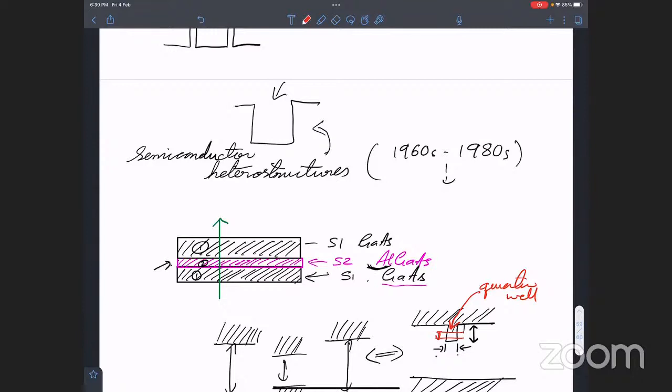And gallium nitride, everybody would have heard, right? So gallium nitride is a compound semiconductor. First work started in gallium arsenide. Then they wanted to shift to gallium nitride because it has a larger band gap, and so on. And that research has now led to huge revolutions in LED research. So we have white light LEDs now, and pretty soon all our energy needs in the entire world are going to be replaced by gallium nitride based white LEDs. Highly efficient. They're going to shoot for more than 50-60% efficiency lighting, whereas fluorescent lighting is only 8% efficiency.